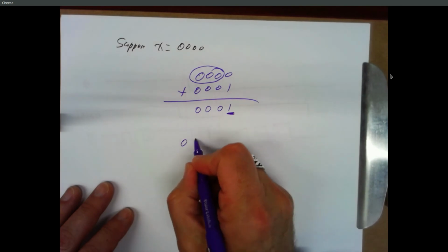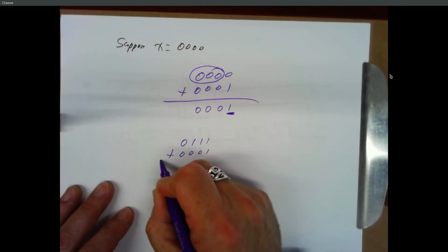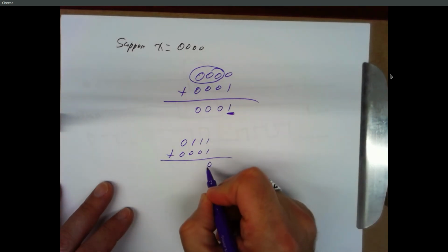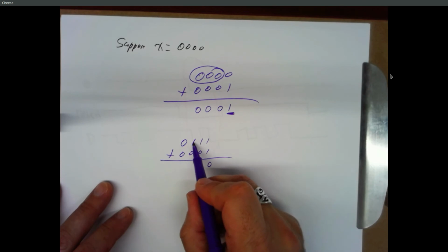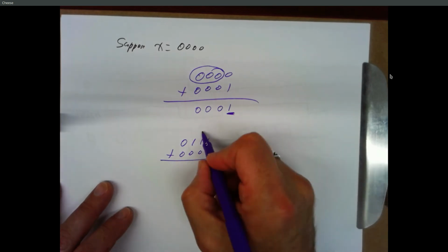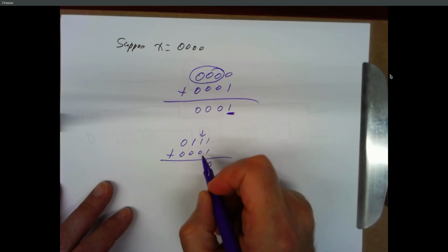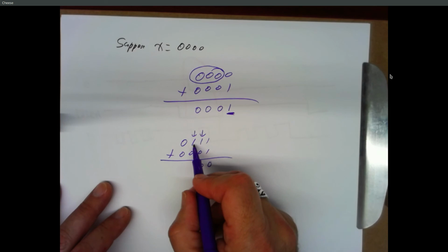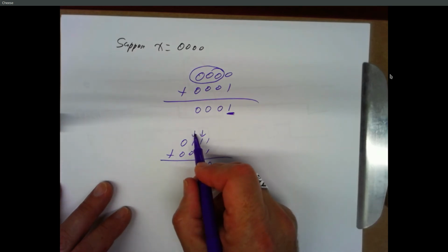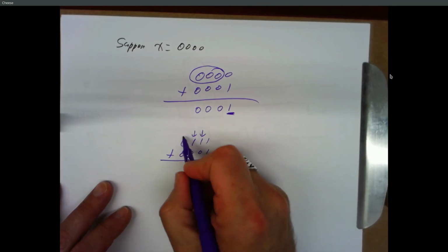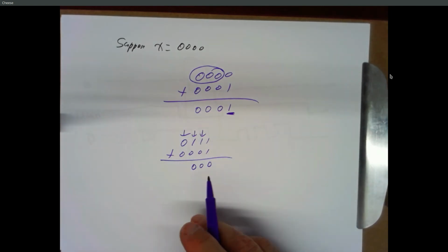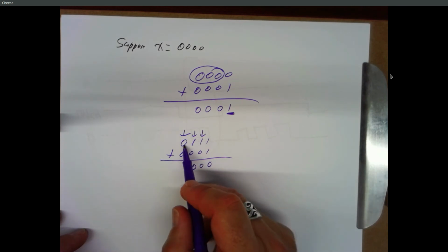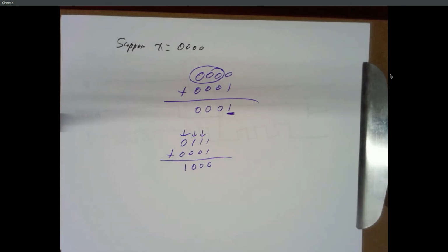But if you're doing this, the half adder is going to say 1 plus 1 is 0. Well, right now, x is equal to 0, 1, 1, 0. That's not correct. But you have a carry come over here, 1 plus 1 is 0, with another carry. Well, now these 2 bits are correct, but this bit's still a 1. But that adder eventually adds that incoming carry of 1 to the 1, gets a 0. And so now you've got 4 zeros for x. That's not correct either. But finally, that last full adder will say I've got an incoming carry of 1 plus 0 is 1. Now your x is correct.